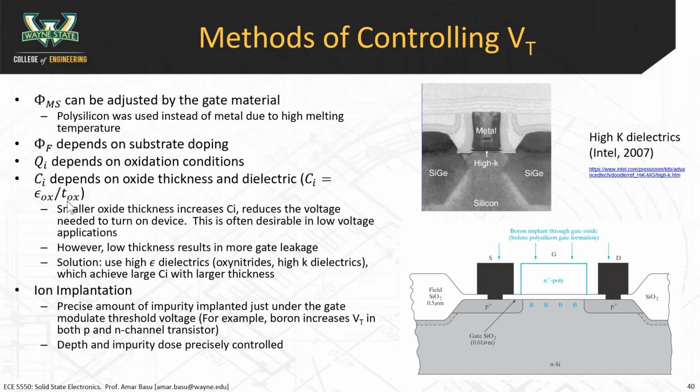How did they eliminate the overlapping area between the two electrodes? This is epsilon A over T. That's right. So here they consider that A is 1. Oh, the area of the capacitance. Yeah, that's a good question. So we are saying that this is unit capacitance. So Ci stands for capacitance per unit area. Okay. To actually calculate the capacitance in farads, they use picofarads or femtofarads, you would actually have to multiply by the area of the device. But this is a unit capacitance. Good question.